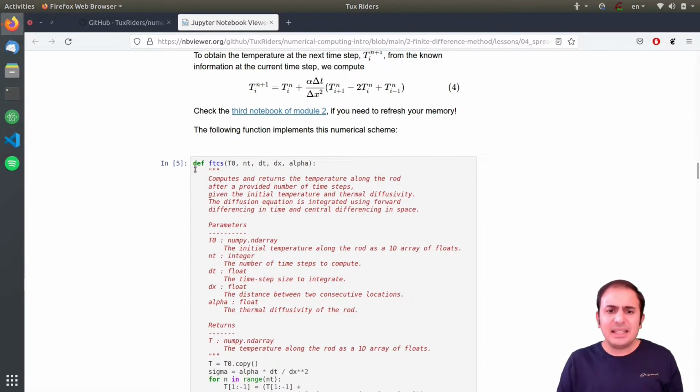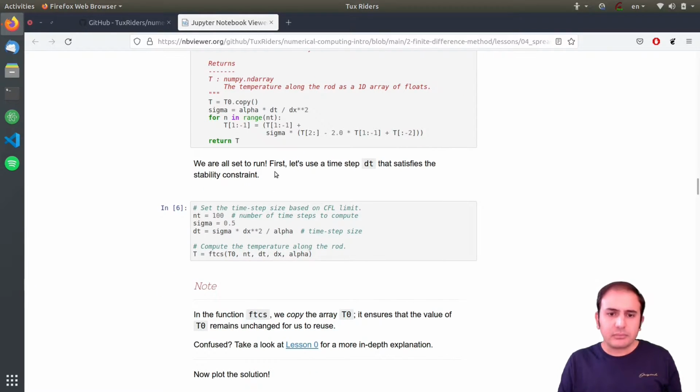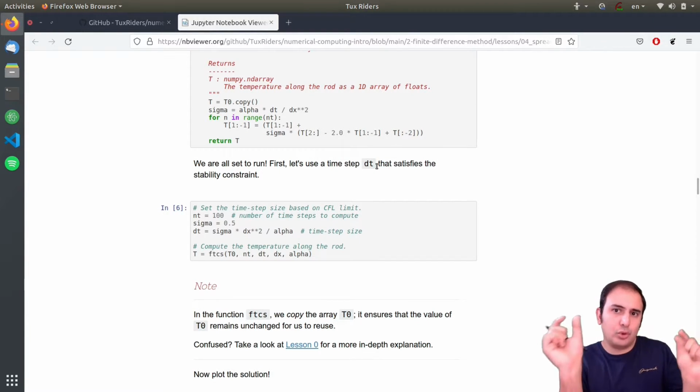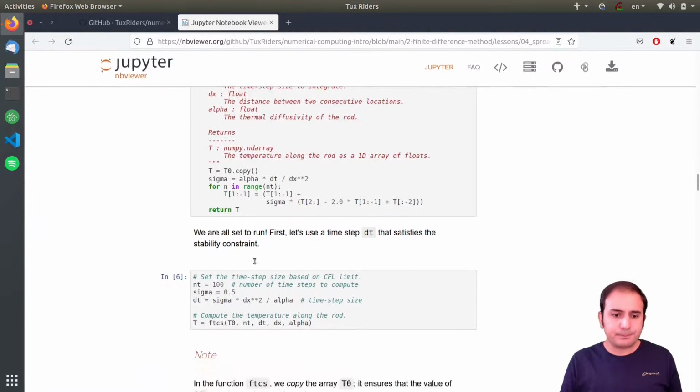It can be easily discretized using forward time and central in space, as we discussed in previous videos. So with a simple loop, we can compute it. And we apply the boundary conditions also. We know the values at two ends. That's why you see that it starts from 2 and it ends with -2. That's because we know the values at two ends of the rod. This is the way that we can apply boundary conditions.